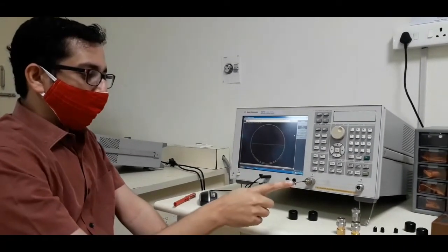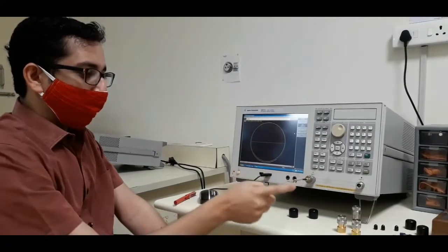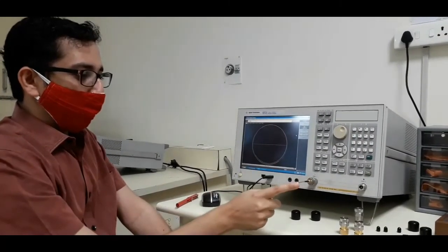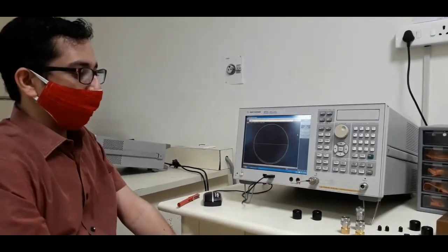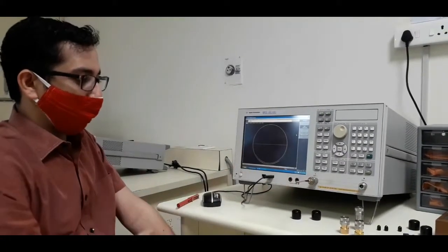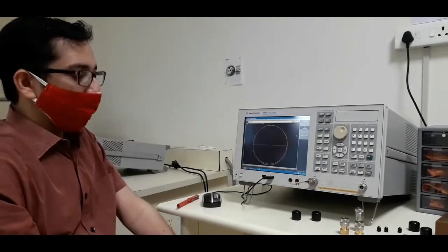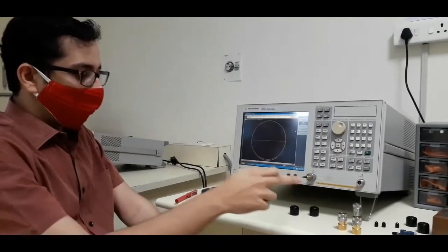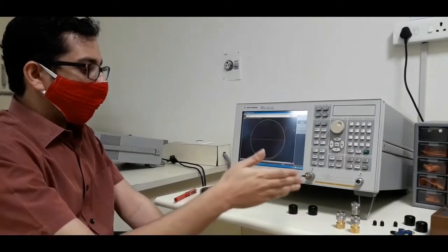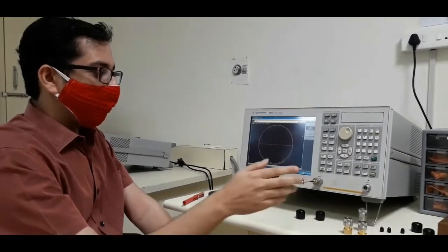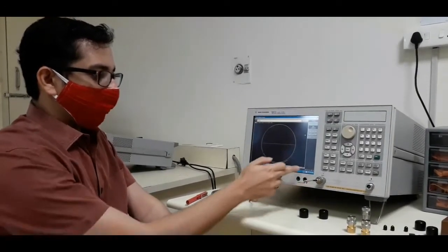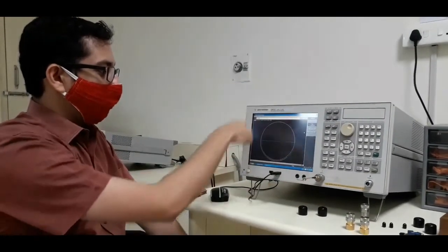Now what I can see over here is that this transmission line is connected to the analyzer over here. So this is the source and this is the load. Now there is nothing connected right now, so that means this is behaving like an open circuit load. As you know, as per the impedance transformation relationship, whenever there is an open circuit load, as a function of the distance, the impedance keeps changing between open and short.